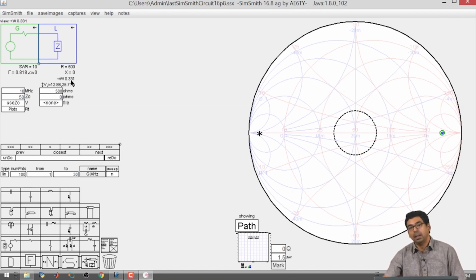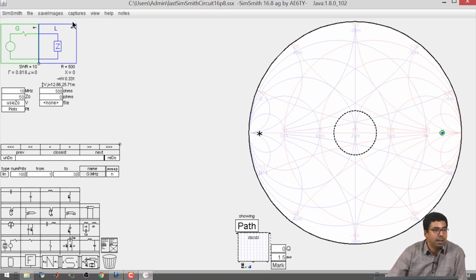Now, if you have mismatched loads, you will not be drawing the rated power from the generator on the load. Since this is a problem relating to signals, signal power is very critical; you cannot afford to lose signal power. An example can be an antenna on the left-hand side and, on the right-hand side, a speaker or something that is processing this signal. You do not want to lose signal power anywhere else, that is the whole objective. So, whatever the rated power is, we would like to get it on the load. That is the objective of impedance matching.